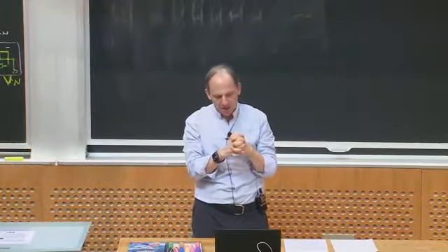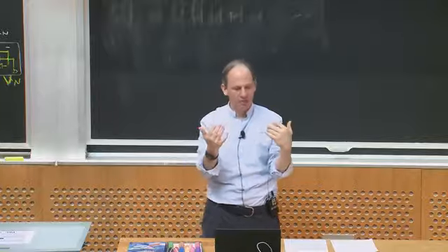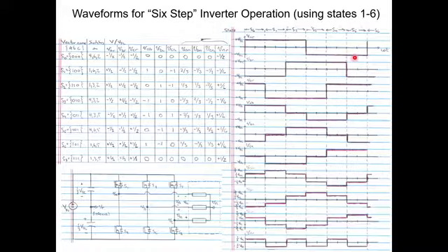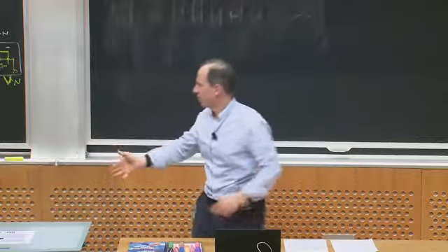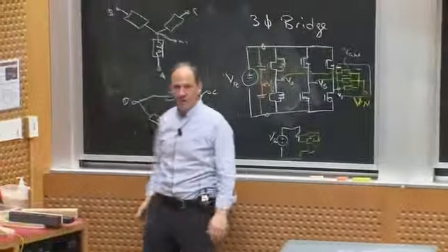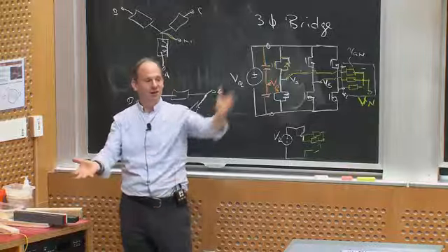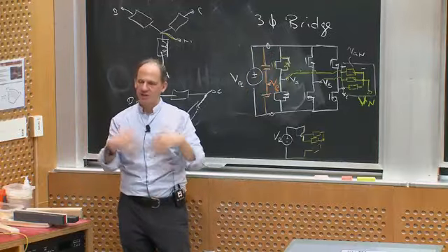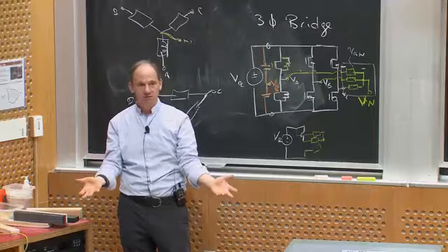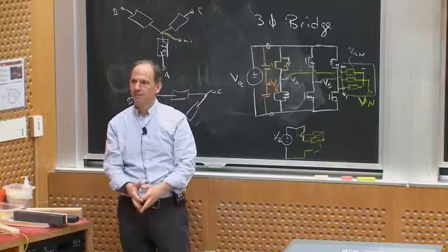Any questions about that? Now, the line-to-reference voltages, these square waves, have third harmonic, right? But because I'm taking the difference between 2 of them to get the line-to-line voltage, shifted by 1/3 of a cycle, all the triple N components disappear. So the line-to-line voltages have no triple N components. Whatever my motor sees, it's line to line. If I'm driving, say, a delta connected machine, it will see no triple N drive. And that's just free because I have this 3-phase inverter structure. If everything's balanced, it can't generate triple N line to line. Any questions about that?